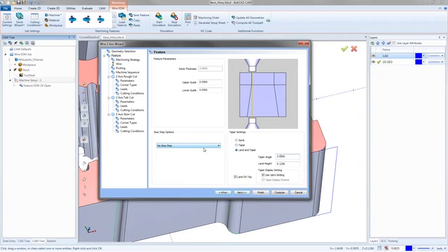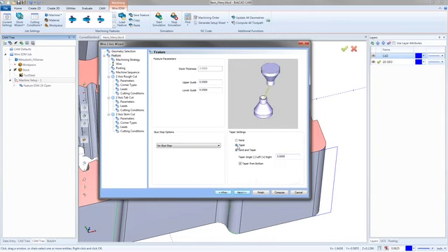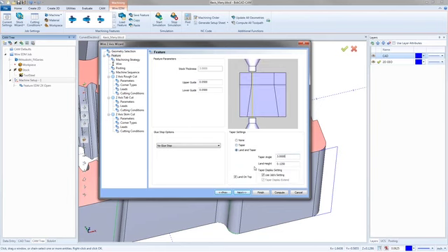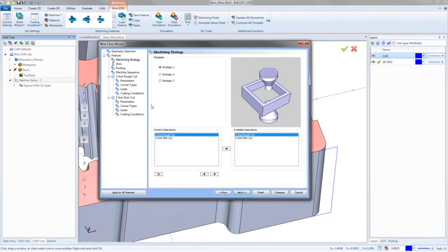So play around with those settings, either uncheck the use job settings and run the taper display extend, and just kind of see which one you like a little bit more. I'm going to do it the standard way. This is the way it should show up with the system. Now, the taper angle can be negative. When you're talking about the tapers, you have a negative to the left and a positive to the right. So you can play around with those settings as well.